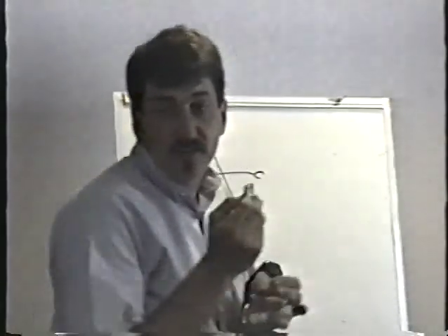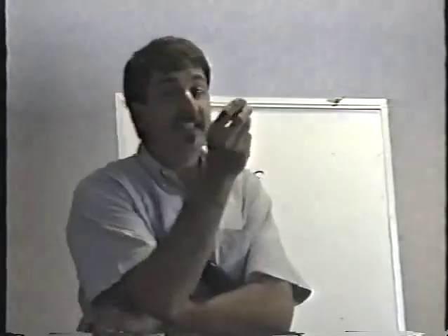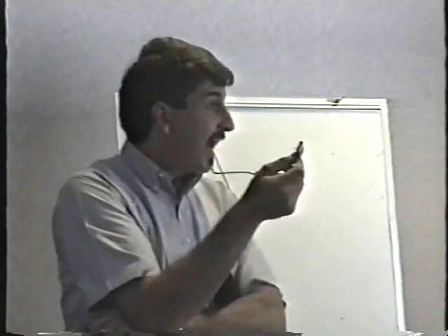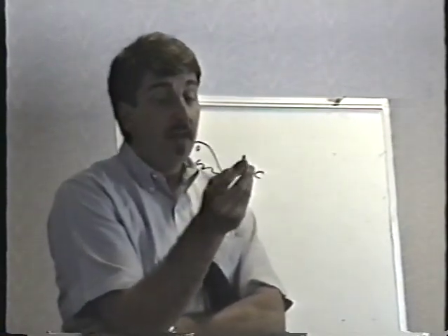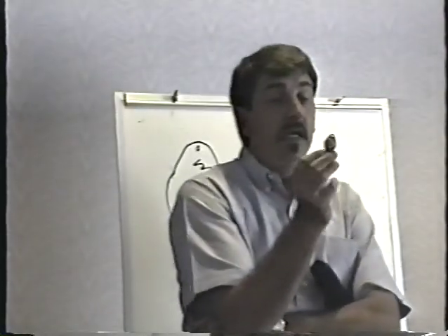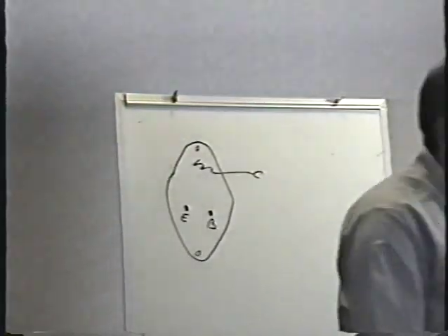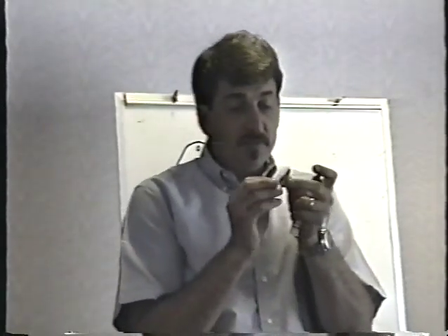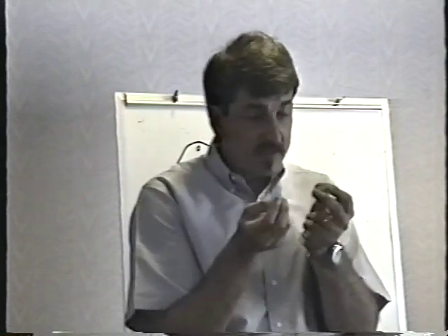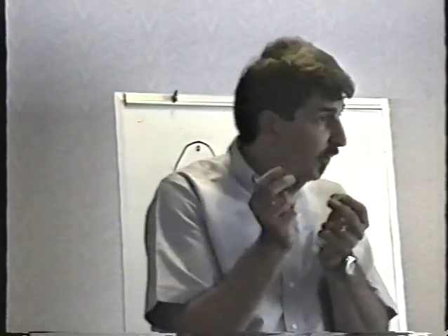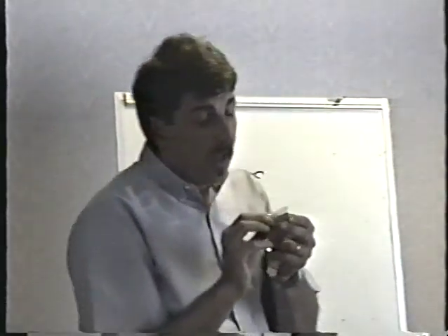Because the collector is the case of these things, it's electrically active. It's going to have some voltage on it most of the time. It can be anywhere from 12 volts to 160, depending on what the circuit is, so be careful. You will always see one of these insulators mounted behind it. When you change the transistor, you must make sure that you put the insulator back. You don't necessarily have to replace the insulator with a new one as long as it's intact.